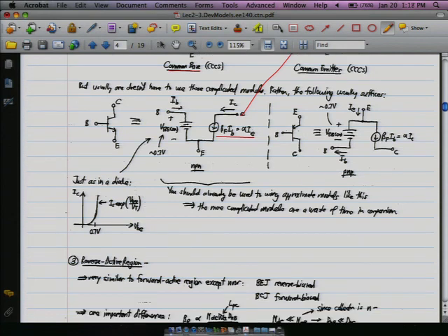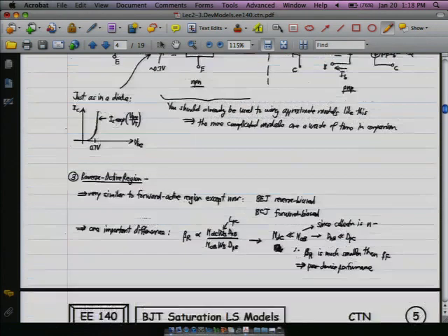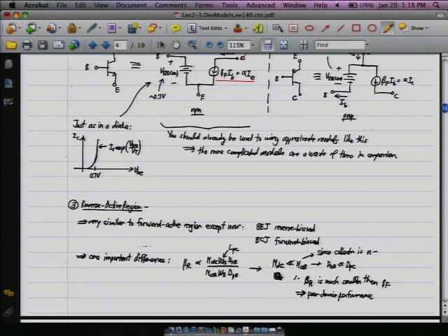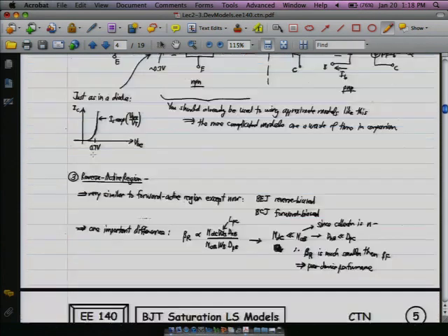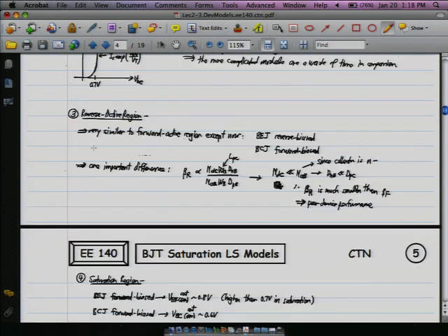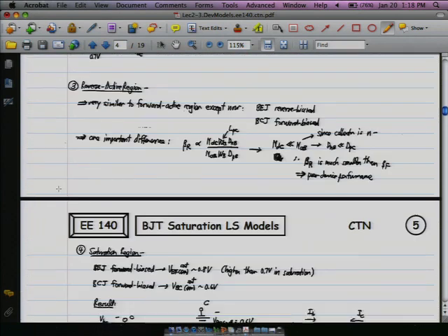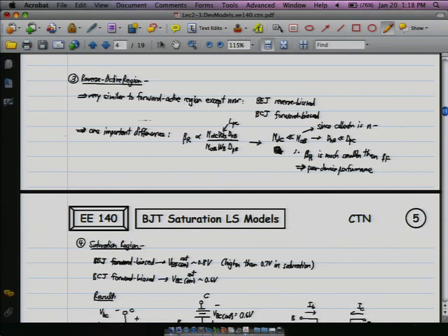All right, so this is basically just explaining why we can represent this as a voltage source, but I'm going to assume that everyone's comfortable enough with diodes. We can go on past that. All right, so the next region to be discussed, as I said before, it's not of great interest, is the reverse active region. Again, it's very similar to what's happening in forward active. You can basically go through the same equations, except the important difference now is that we have this alternate value for beta. It's beta reverse, now beta R.